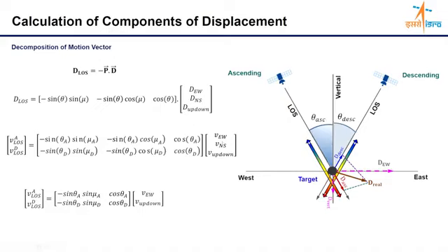So by this practical example of the satellite geometry, if you drop the north-south component, then it is justified. Justified in the sense that VNS denotes the displacement along the north-south direction, and north-south direction means the satellite is moving from the north pole to south pole or south pole to north pole. So the satellite is moving along the north-south direction, which means whatever we are investigating along the north-south displacement cannot be investigated with great accuracy.